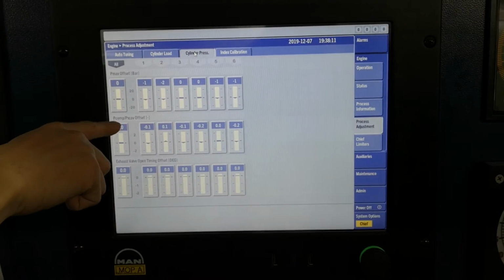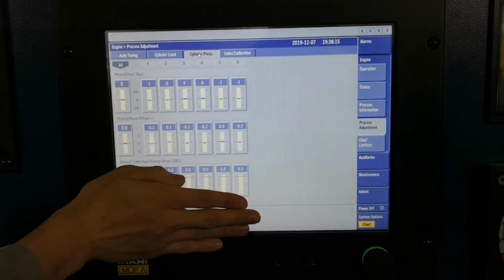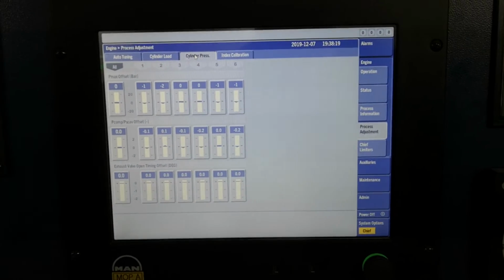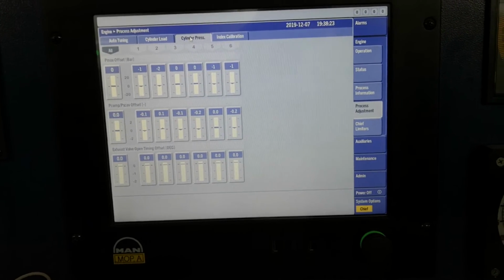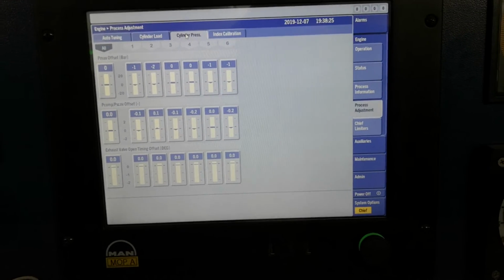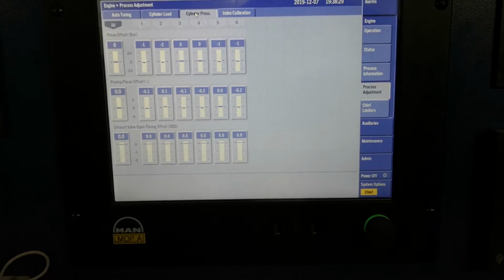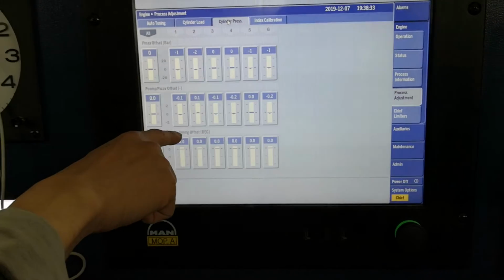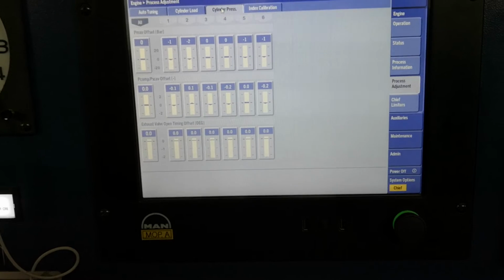You just control the P comp, P scavenger ratio here. Actually, with Wärtsilä they control here and adjust this one. No, Wärtsilä adjusts timing. For timing you can have a separate unit, a little bit early or a little bit late injection. That is a separate function. Also for the exhaust valve you can have early opening or early or late closing.